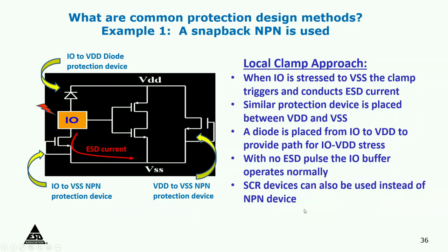So that is how the devices are built to protect. I mean, I'm trying to give you the most simplistic pictures. There are a little more complicated things that go on than this. But that's one way of doing it. But the problem of protecting this way is that it introduces capacitance and leakage. For high-speed applications, I don't want that capacitance so high. This could be something like 1 pF of capacitance, and I can't handle so much capacitance. I want to be able to reduce it. So people look for innovative ways to reduce the capacitance.